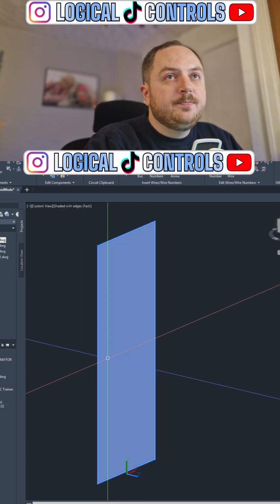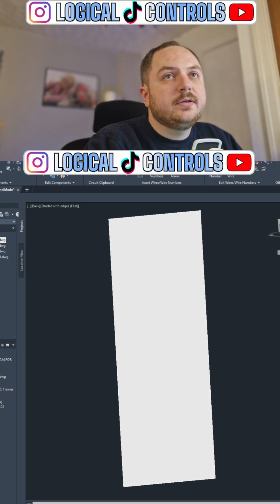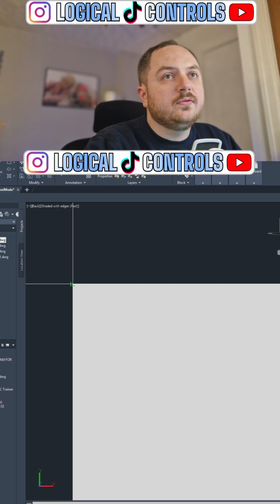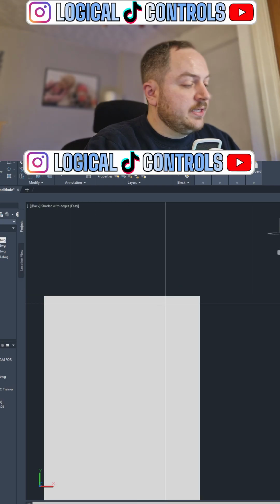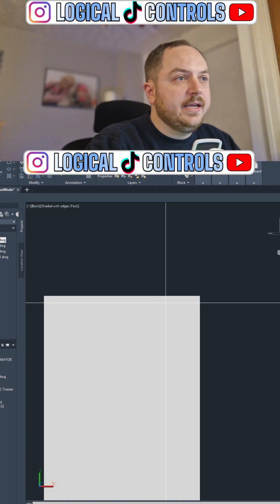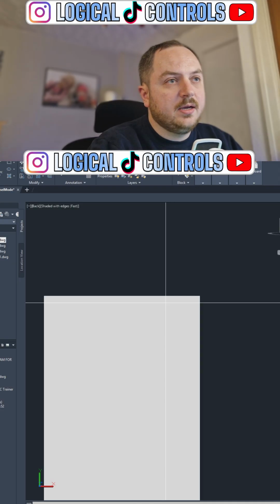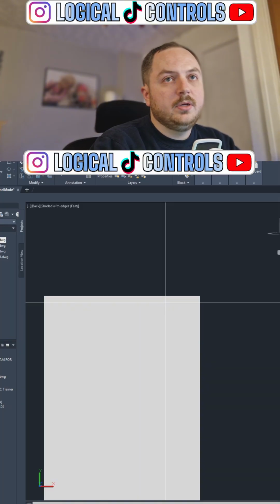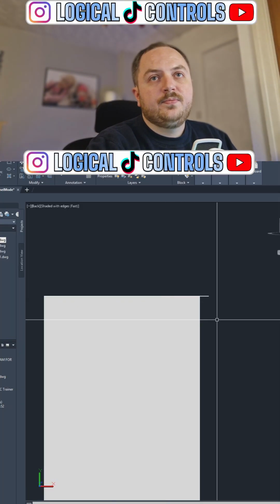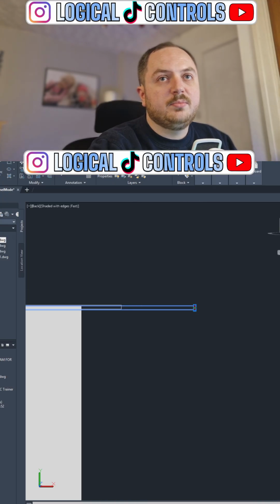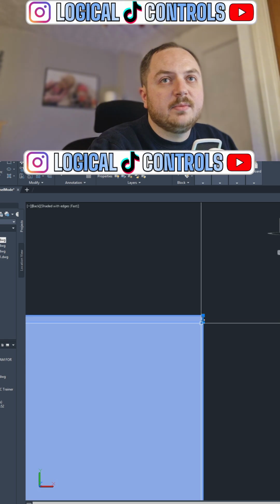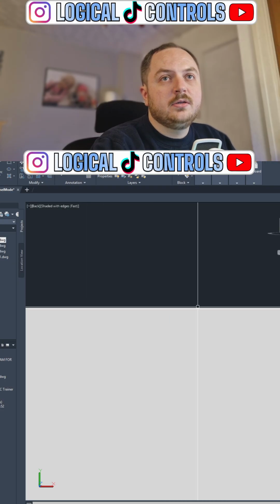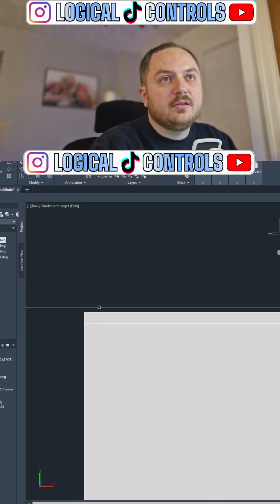Right, so let's go behind this mounting plate. And same story again, I just use rectangles for almost everything. Let's make that, I'm going to say 800 wide, but it'll be a bit less than that, but you'll see what I mean in a minute. So 800 wide by, in fact, 1.5 mm. So it obviously goes over a bit, but I can just pull that back in. I don't know the exact dimensions that I've made this mounting plate. Let's pull that in by 3 mm and pull the other side in by 3 mm.